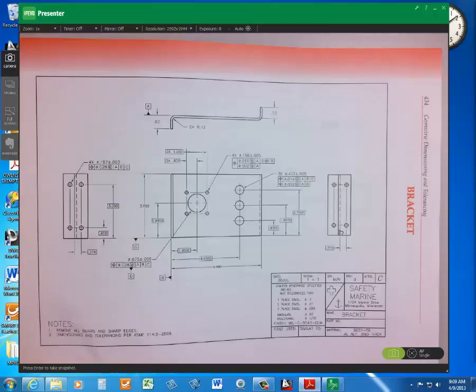It's a composite positional tolerance using rectangular coordinate dimensioning. All right, that's the first thing. The upper part of the feature control frame specifies a pattern locating control of 10 thousandths at MMC. And the pattern of features must lie as a group relative to datum A and D at maximum material boundary.